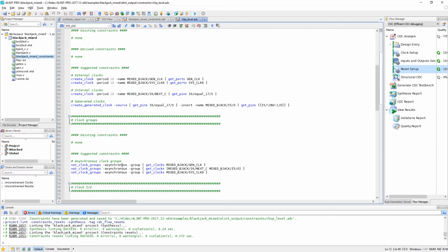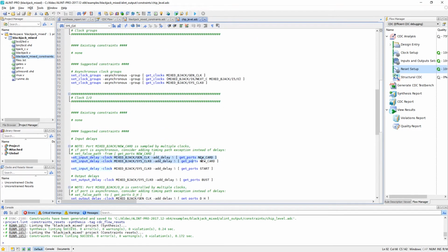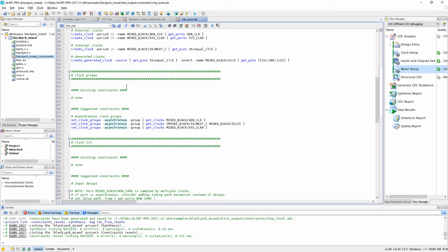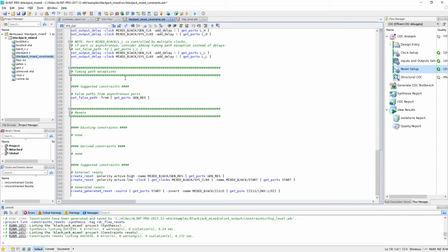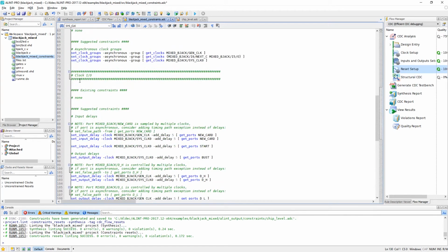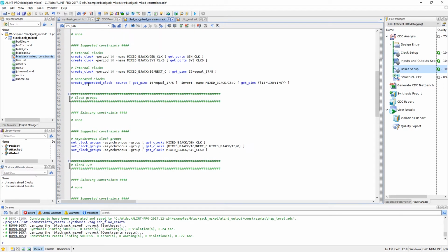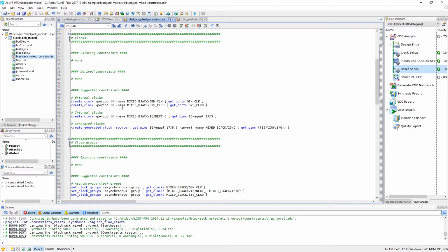Going over these constraints, I can choose which ones I want to be applied simply by adding them to my project's constraint file. As I want my constraints to be comprehensive, I'll just go ahead and copy the entire file over. Here, it's particularly nice to have this formatting for different constraints. Now that I have a solid foundation to start fine-tuning these commands, I can go over each command and modify them as needed. For example, as the tool will just use default values for clock periods when frequencies are not explicit, I can go ahead and change these options to the desired values.